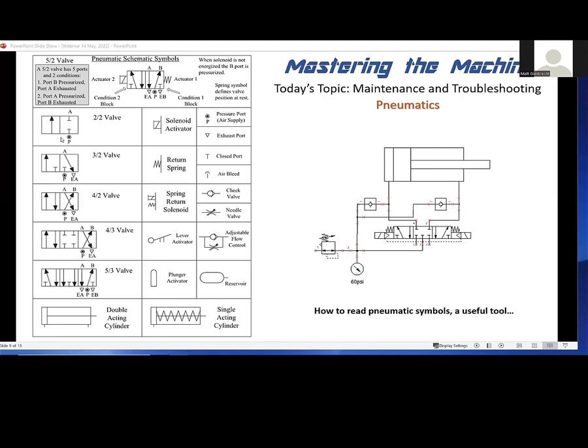There's a 2-2 valve. So if I shift it to this side, it's just completely off. It blocks the port. If I shift it to this side, then it allows pressure to pass through it. I actually have one of those cylinders that you would use with that here. And in this case, you put air in here, and it's a spring return, right? And if you pass it to the other side, you would probably unplug the port and just let the air pass back through the valve, right? So this 3-2 valve is probably something I would use with that.